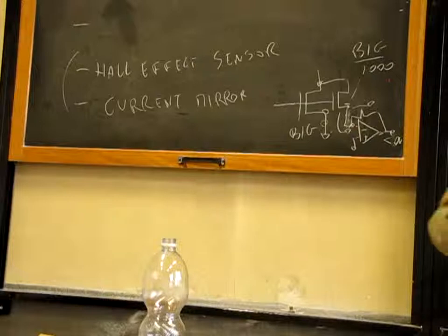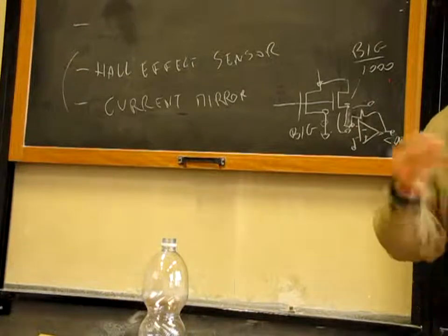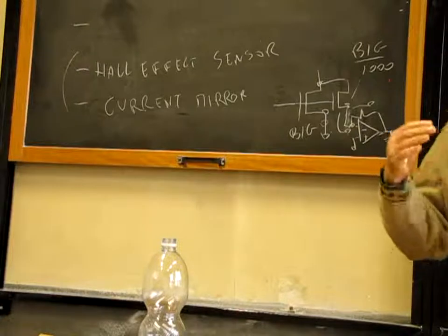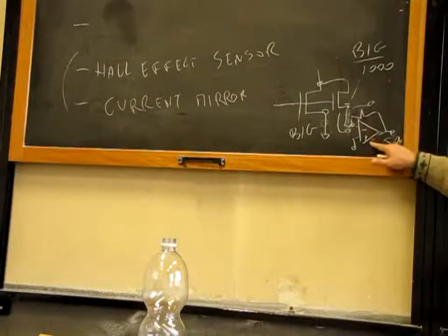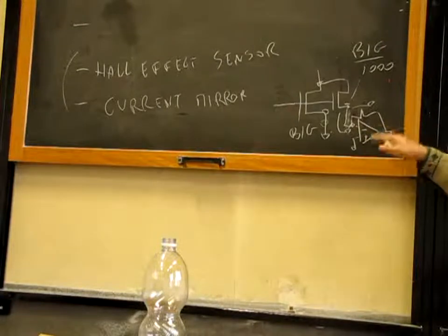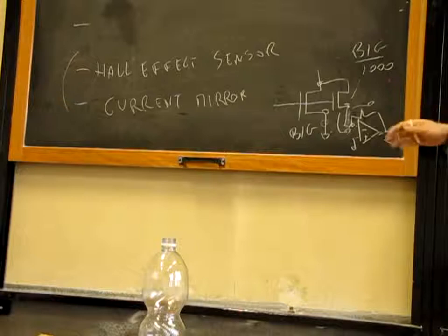Usually your control circuits don't have double symmetrical power supplies, positive and negative with respect to 0. There is just a single supply. And so you need a positive and negative supply voltage for this op-amp, and the circuit would have to be able to handle negative voltages. So that was a good idea.